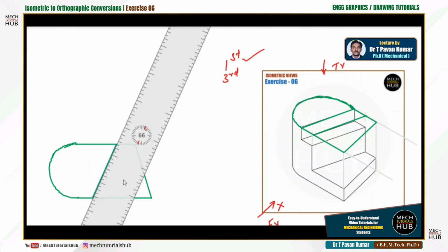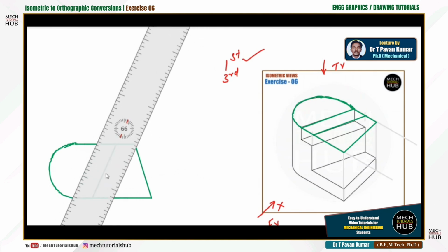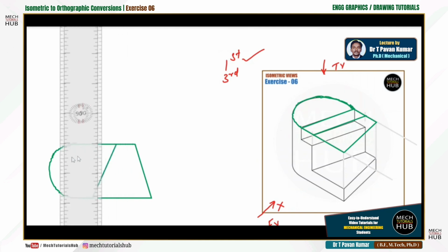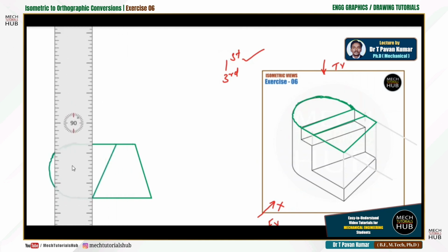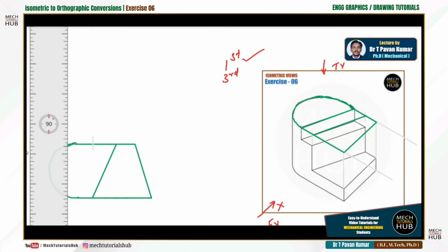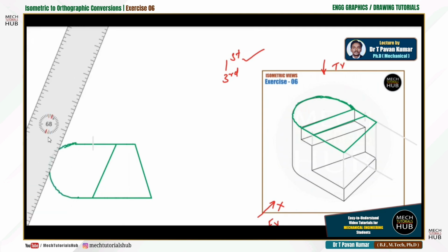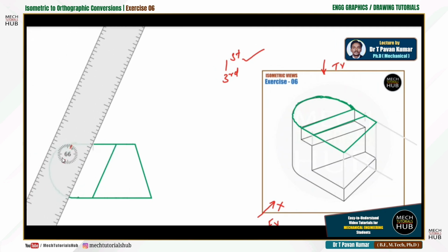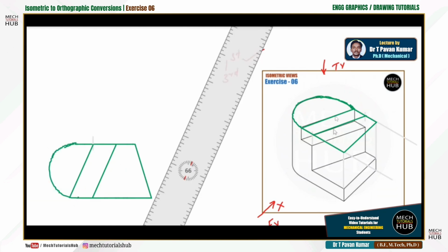You will be given all the dimensions in the question, but just to make you understand, I'm doing all this. Before drawing one more parallel line, align your drafter to 90 degrees where these two points should be in contact. So I'll consider one intersection line by using a construction line. Then rotate your drafter and align with the line you have drawn just before, and draw a straight line. Got it.